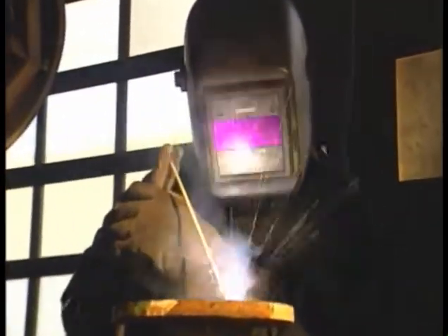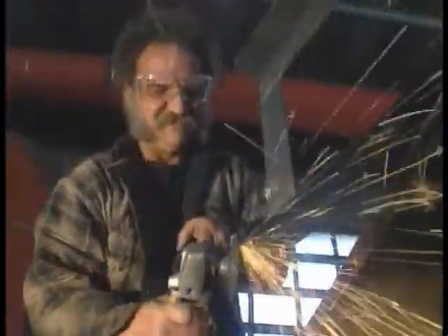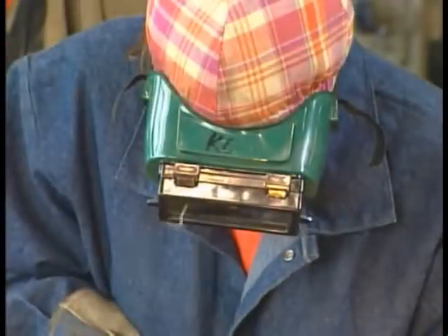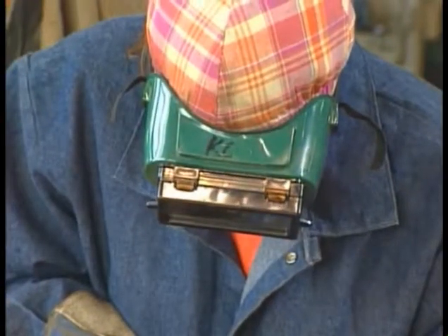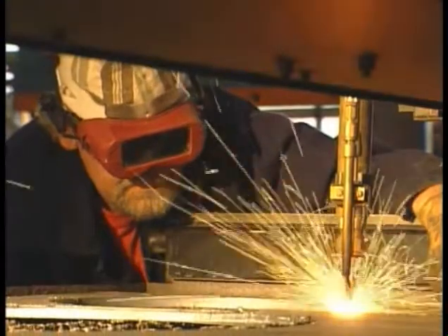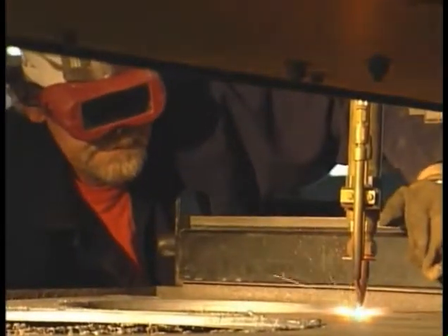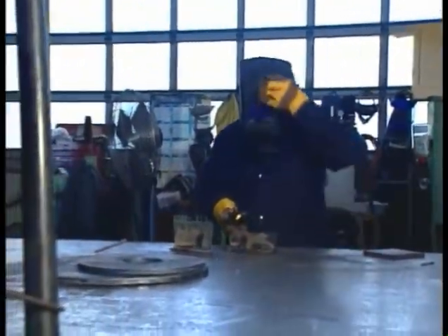Eye injuries occur from intense light, ultraviolet, and infrared rays emitted while cutting and welding, and also from flying sparks and hot slag. Goggles protect your eyes, and many have lenses you can replace when necessary. Goggles are attached firmly around your head so they can't slip off while you're working. A face shield or hood provides more protection than goggles since it covers your entire face. Face shields are also easier to pop up and out of the way if you need to use normal vision. Face shields come in both clear and tinted styles.